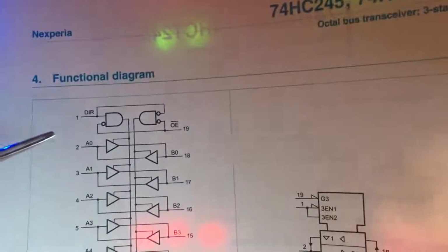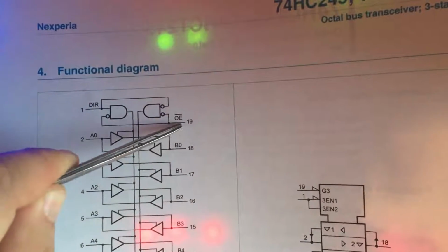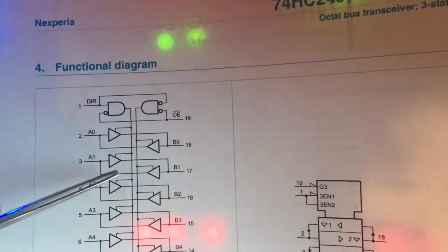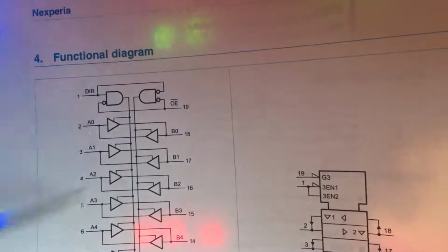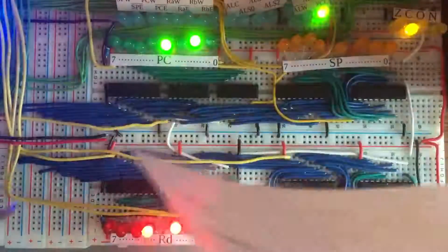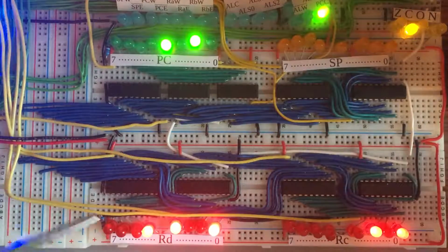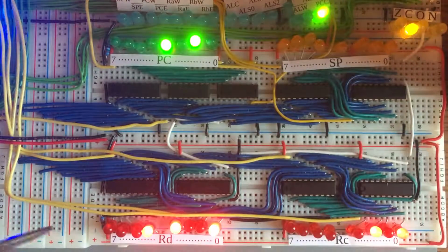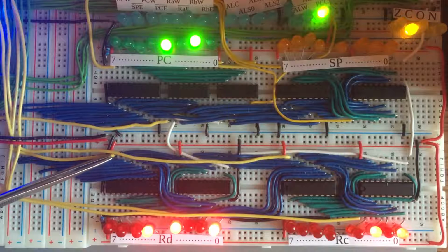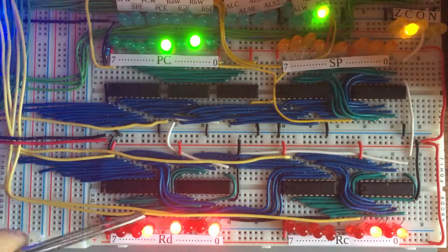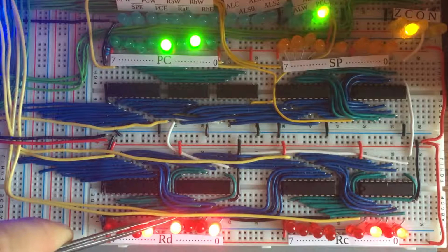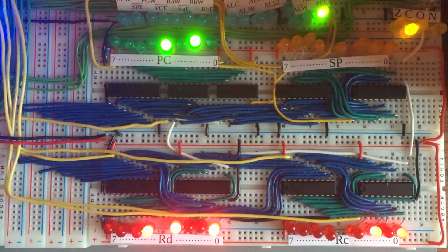And if we enable it, there's an output enable signal. If we enable that chip, then it's going to connect those signals onto the blue wires, which is the bus. So that is a signal which comes into this chip, which is over here, and that's our enable signal. That's the D enable signal, and that's the D write signal. So that's how that works.